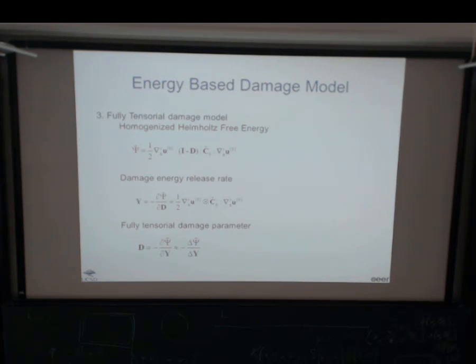Of course, you can do something fully tensorial, right? So with this framework, now if I can extract a fully tensorial damage model, again, the red one is by computation. From thermodynamics, then you can compute the energy release rate from here, and you simply, again, you can take finite difference, this one by computation, and this one is the undamaged free energy, and you can then extract the fully tensorial damage model. Right? So if necessary, you can do this. So the framework is here.